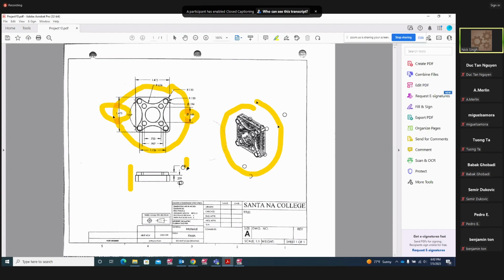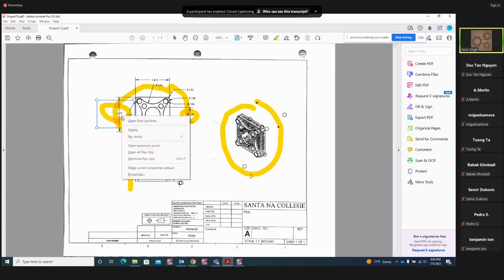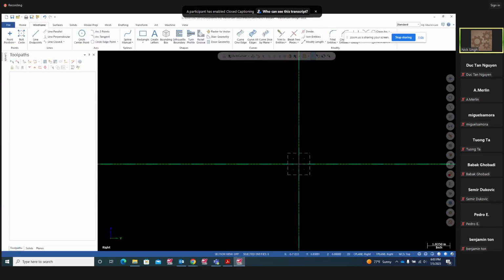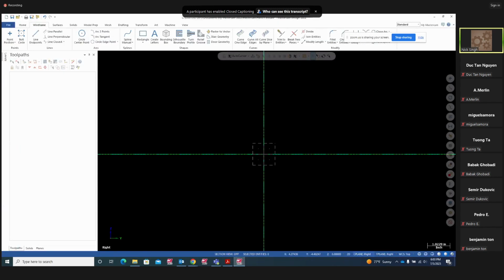I'm going to create a rectangle first, of 1.475 at z0. Then I'm going to start creating these holes. Everything we're going to do at z0 right now, and then we can move it further down. Okay, so 1.475 rectangle at z0 in construction plane right.